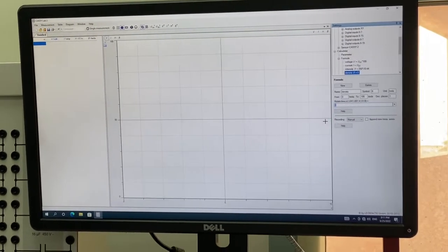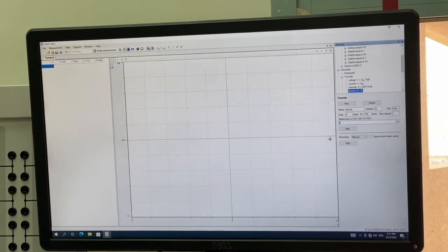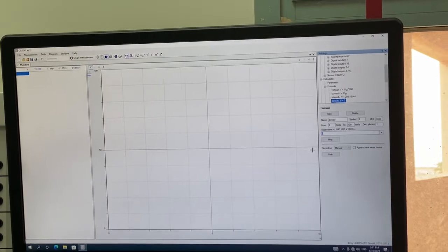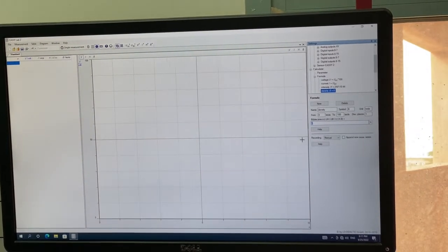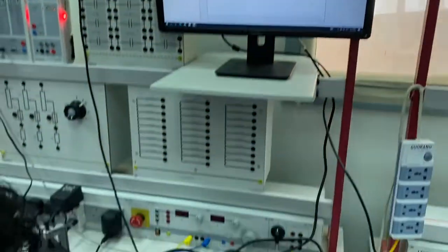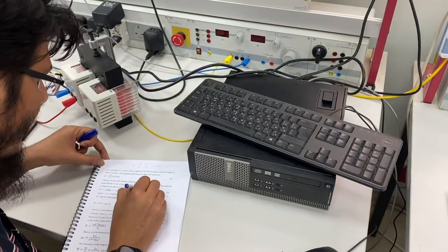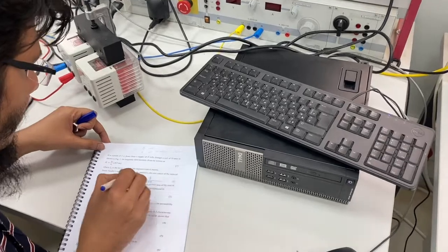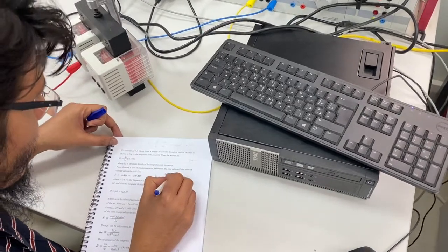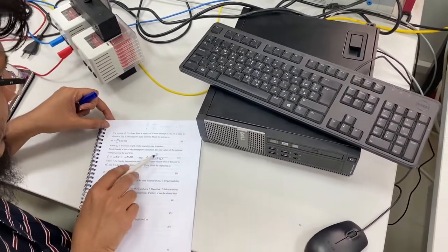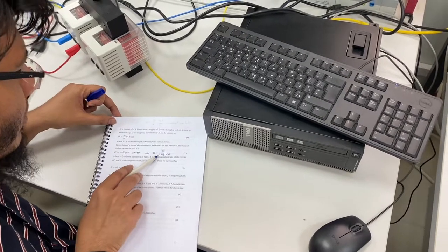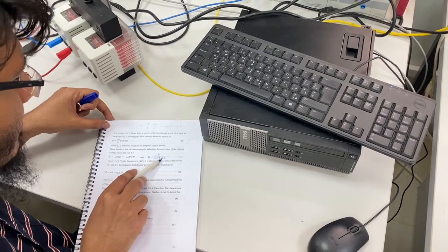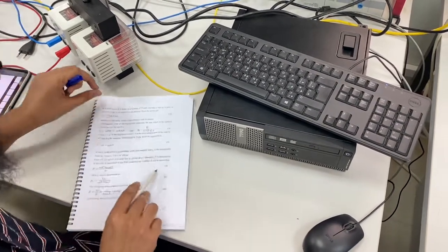Do you have a pen? Anyone? So this one, just try to see here. The equation is this one. So B equals E divided by omega, which is what? 2 pi F, right? 2 pi F N A. Okay? So E is the voltage, we know. 2 pi is 3.14. F is the frequency, 60 Hertz. N is the number of turns, and A is the area.